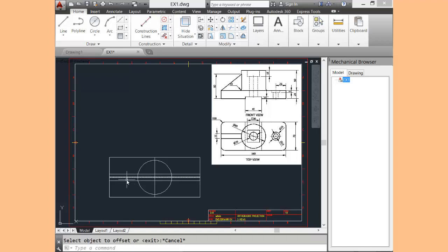So these two lines are representing our web, but our web is not along the base, it's only to this circle. So we have to cut a piece of these two lines. We'll go to modify again and introduce our two commands. Erase command, select object. If we select this object and click enter, we erased the whole object. Go back, undo. We don't want to erase it all, we want only a piece of it.